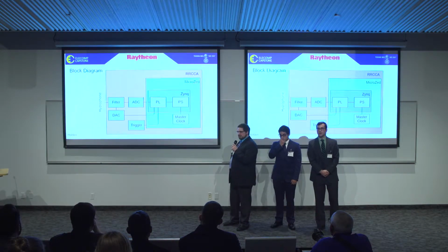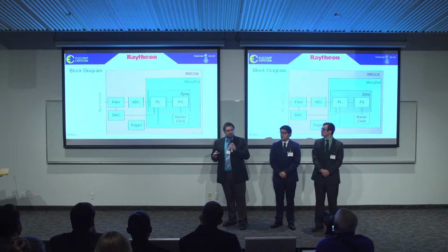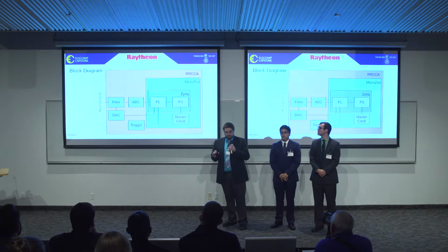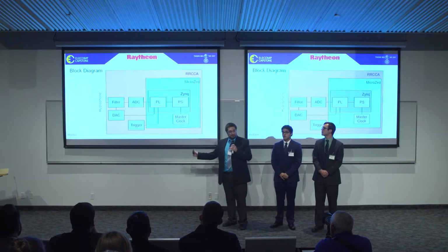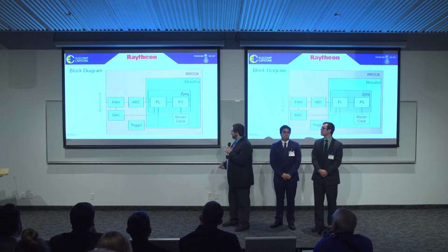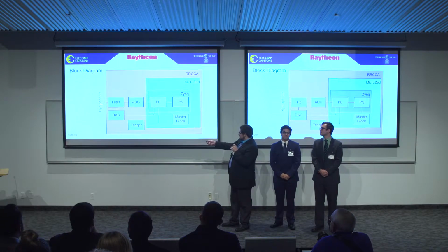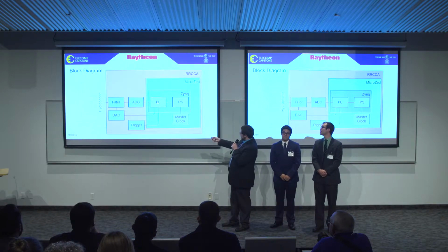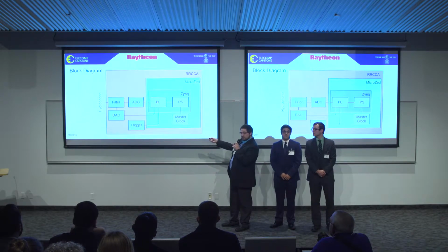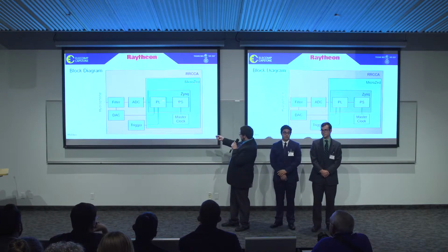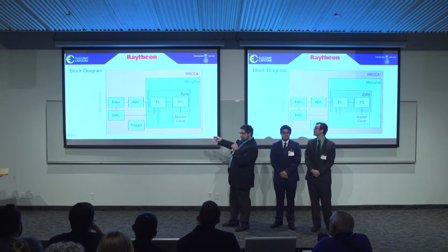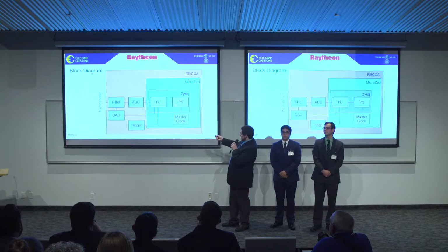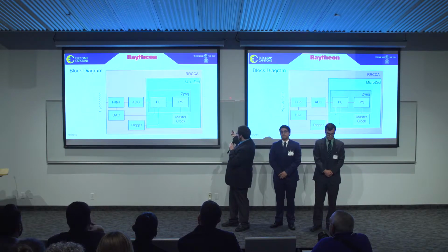As such, this is a heavily boiled down version of our design so far. Please note the real diagram takes up more than the entire wall, and we have like 10 pages. The hydrophone's analog voltage signal is sent through the analog filters off to the analog to digital converter, which converts into 24-bit integers, which go into the programmable logic, which converts to 32-bit floats, which are saved in block memory in the PS, which is read by the processor, put into packets, and sent over the Ethernet link to the PC.